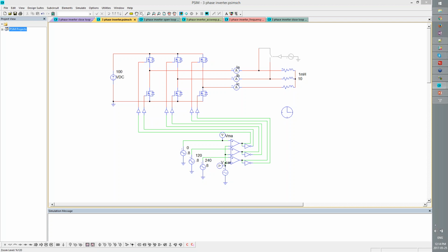I won't pick it up. It's underneath my laptop stand here, so that's going to be a little bit difficult to show you, but there's the HIL unit there, and this just slots in at the front like so. I have a JTAG connection to flash the DSP. So this is the XDS100 version 2, and this just slots in, and this is how we'll be uploading the code to the DSP.